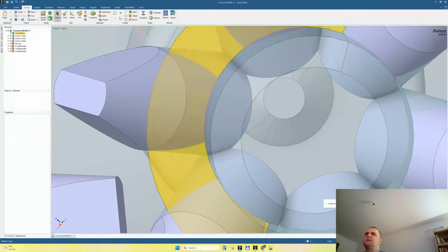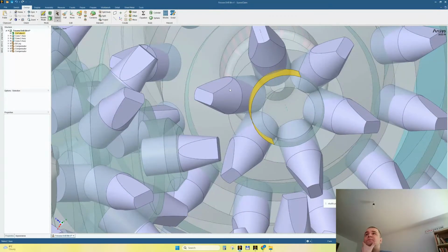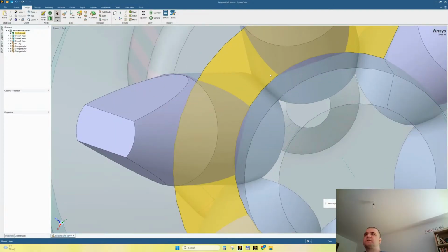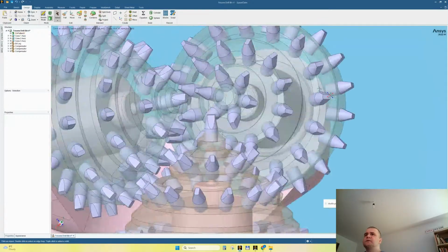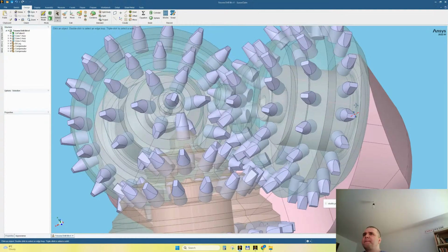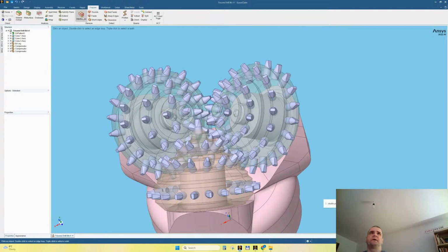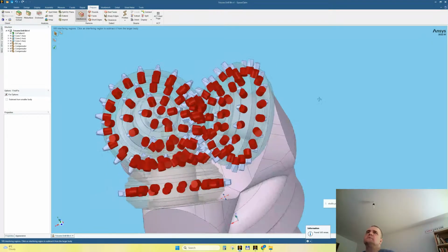These initial bits are colliding between each other and also with the fixture. Control S to save. All right, we have this option, prepare interference, and let's look. Besides the teeth, which will clearly interfere, no other interference.